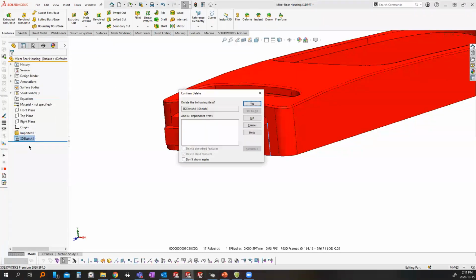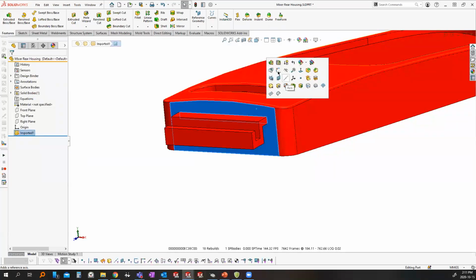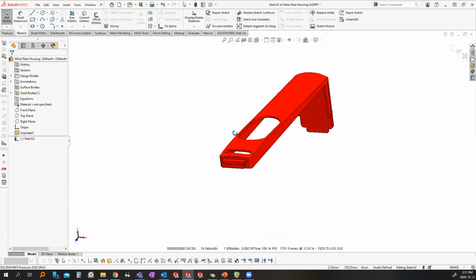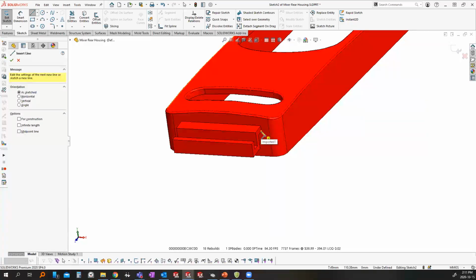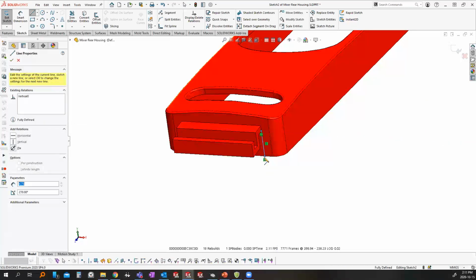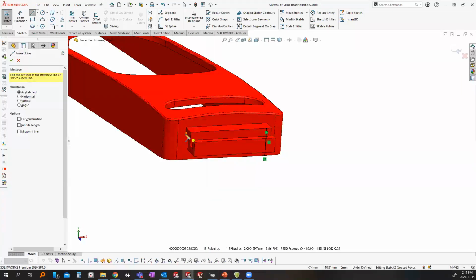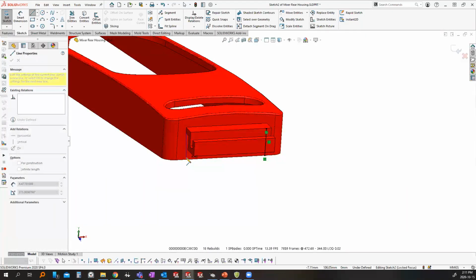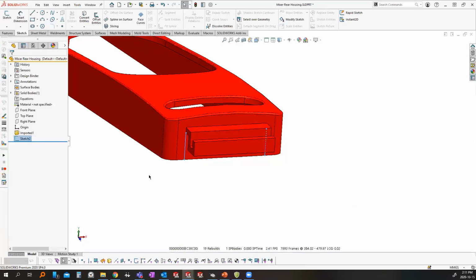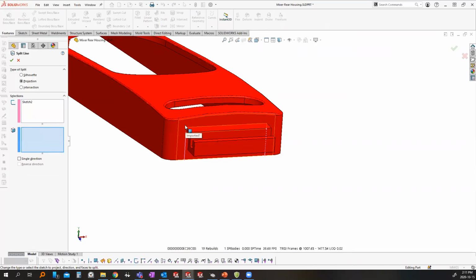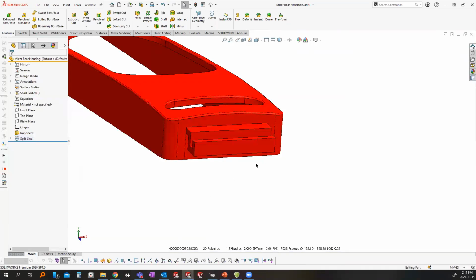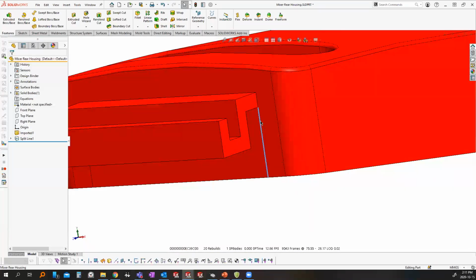Well, if that fails, let's maybe just remove the 3D and we'll revert back to our traditional 2D here. That's fine. And we'll try it again. There we go. So I'm just dividing up this face here. You can see I have my edge, and therefore I can get my parting line from that.